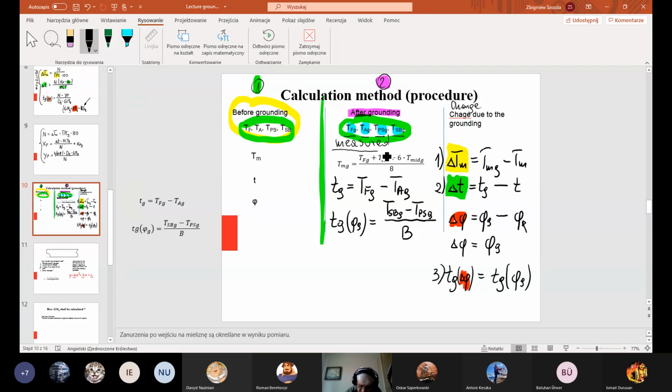It is very easy to say that you have to measure drafts after grounding, but I hope you can imagine that it is a very good question how to do it in practice. How to do it in practice when the ship is grounded, there are waves, the sea surface is not calm, everything is moving around, and the text just says measure drafts after grounding.